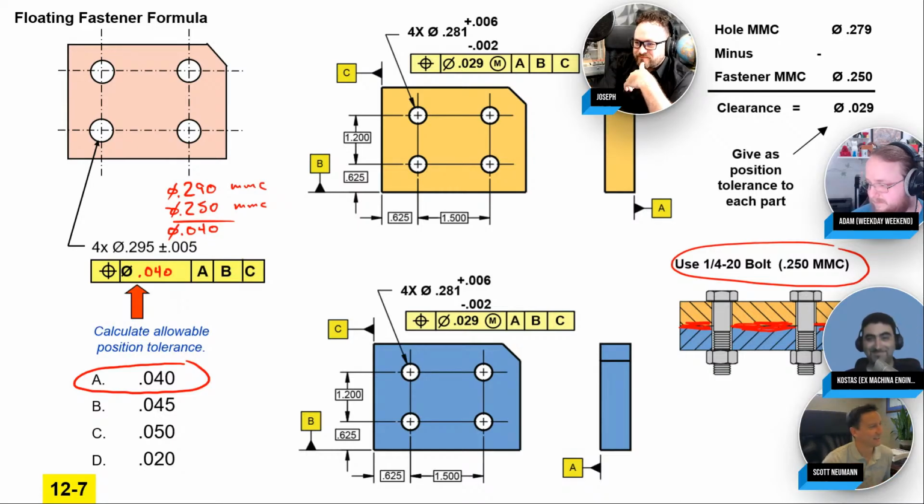Yeah. So yeah, machinists usually care about nominal. That's like what they aim for. I'd recommend to aim for the middle, 295. But yeah, if you're a design engineer, you got to look at your worst case.